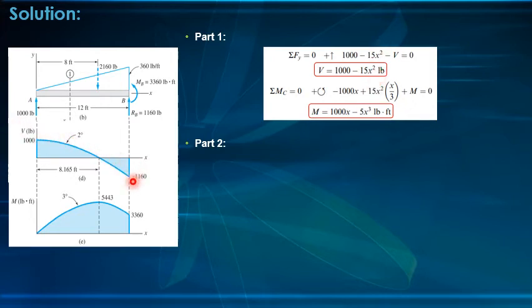And then at this point, wherein your x is equal to 12 feet, palitan nyo to ng 12 feet. And you will arrive for negative 1,160. That is your shear force at this point. Okay, next, sa moment naman. If we do moment, if we substitute 0 here, you will have a 0 moment here. Okay? So, continuing from, ituloy-tuloy mo lang siya i-substitute, magkakaroon ka ng value. Ay, magiging ganito yung plot mo, hanggang sa 12 feet.